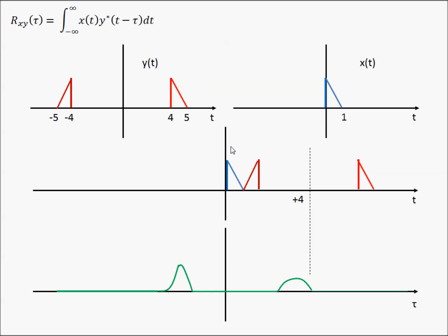That is because the cross-correlation is really a measure of the similarity between the signals. And since this triangle is identical or equivalent to this triangle, the signals are going to be more similar, so the peak is going to be higher. This triangle is less similar, although it has the same area. The shape is less similar than our x(t), so the value of the cross-correlation is going to be less. You should confirm this by doing out the integral, but it is going to be so.